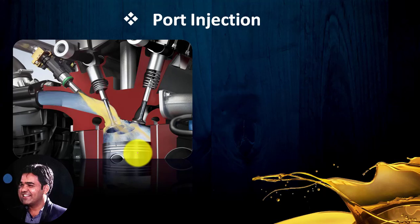In the port injection system, the injector is placed on the side of the intake manifold near the intake valve. As you can observe in this figure, the injectors are placed on the side of the intake manifold near the intake valve. This injector sprays gasoline into the air inside the intake manifold. The fuel particles mix with the air in a reasonably uniform manner, and this mixture of gasoline and air then passes through the intake valve and enters the cylinder.